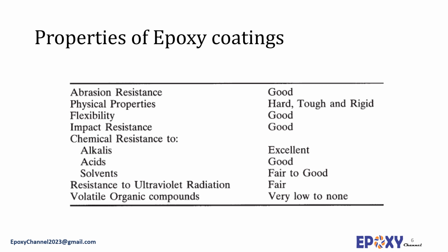Epoxy resins' abrasion resistance is good, their flexibility and impact resistance are comparably good, and their chemical resistance to alkalis and acid is perfect. Epoxy resins show perfect chemical resistance properties and good mechanical properties, but they are susceptible to UV radiation and are not often suggested for outdoor applications. Among epoxy resins, cycloaliphatic resins exhibit good outdoor aging properties, as they contain no aromatic rings which absorb the UV radiation and start the degradation process.